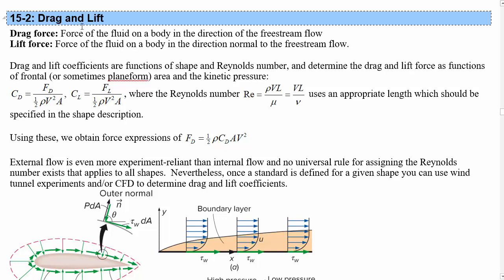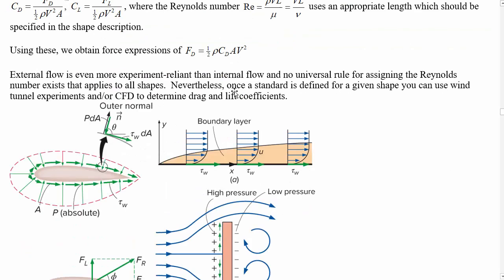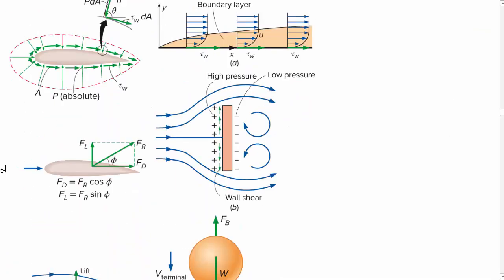15.2, drag and lift. Drag force is the force of the fluid on some body that's in the fluid, in the direction of the free stream flow. So if we have flow moving from left to right here in the direction of this arrow, the drag force would be whatever force this fluid creates in the same direction, in contrast to the force perpendicular to that, which we call the lift force.